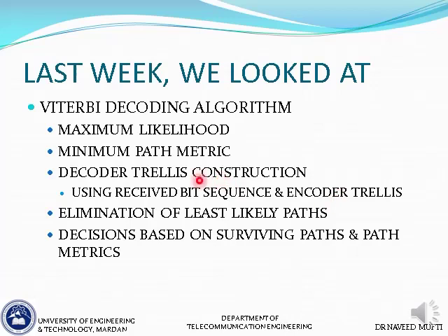What you have to remember is that the decoder trellis will be unique for every received bit sequence for the same encoder. So while the encoder trellis remains the same, that is generic for a specific type of encoder, the decoder trellis will change for every received bit sequence.